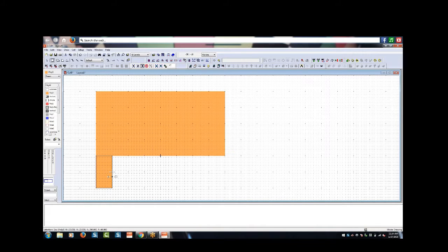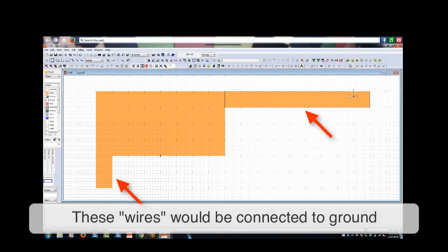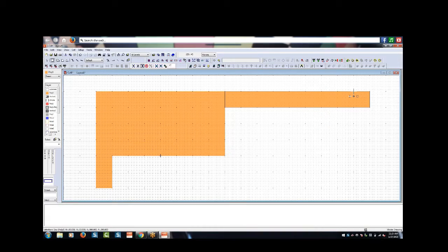Okay, so we might put a wire coming off of it, and these are really broad wires. And then we can ground it to different points on the chip, on the final chip product. And that way all the stray charges that might be on the poly 0 can be drained away. Okay? But for the purposes of this cantilever exercise, you don't need to draw those in unless you want to. All right, so now we got our first layer.